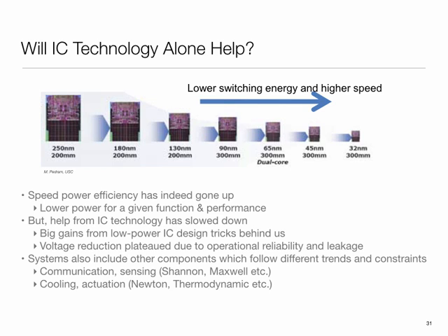But what has happened is this voltage reduction has plateaued. You're not seeing any further reduction, because we really cannot, since at that stage reliability begins to get affected. Reliability as in whether your computation would be correct or not, and also leakage that we were discussing earlier. When you keep things powered off, as the voltage has gone down, this leakage current begins to go up.